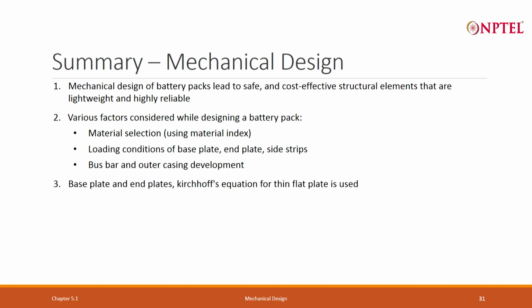For the base plate and end plate, either we solve the Kirchhoff equation for a thin flat plate, or we use the direct stress-strain formulas from books. What I have used is Roark's book; you can use any other books also. We have also discussed what free vibration and forced vibration are. In free vibration, the external force is 0.